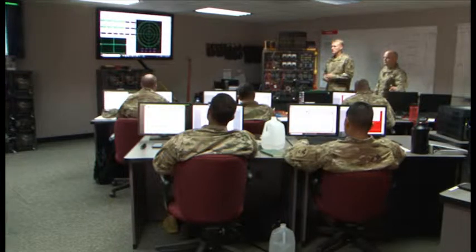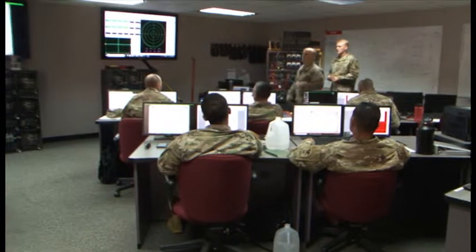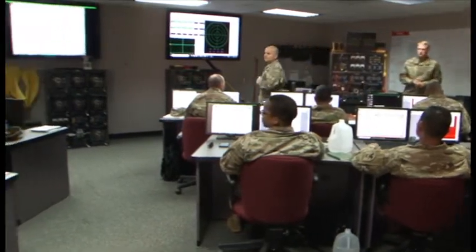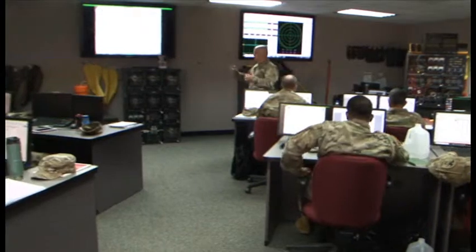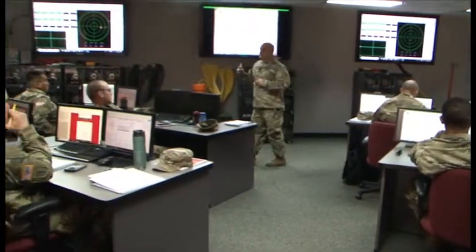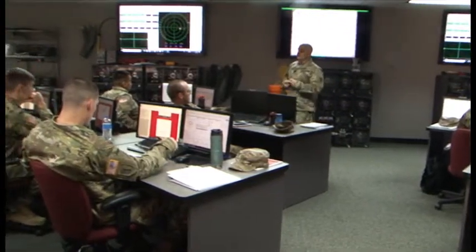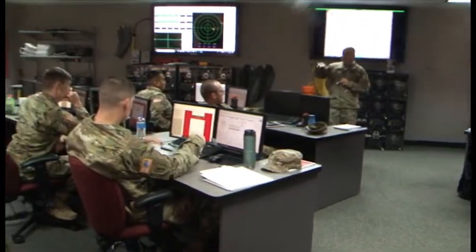But where were you talking about phase angles and all that? Okay, so you said it was lagging, right? You saw that the current was lagging the voltage in there, and the ELI the ICE thing confirms it, right? Because that was an inductive circuit. It had resistance in it, but it was an RL circuit, which means it's not going to be in perfect unity. There is going to be a phase angle.